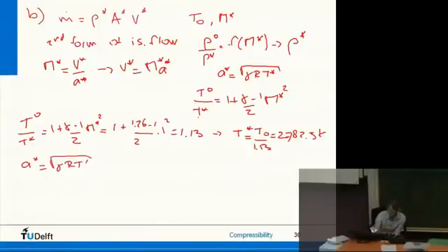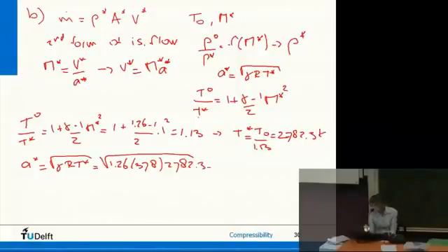Okay, temperature. So now we can find the speed of sound very easily. Same trick, square root of gamma R T. Gamma is still 1.26 in our case. R was 378. Temperature we just computed. Square root. So that gives us a speed of sound of 1151 meters per second. And since Mach is 1, this is also V star, right? Because Mach is 1 in the throat. So that gives us V star.